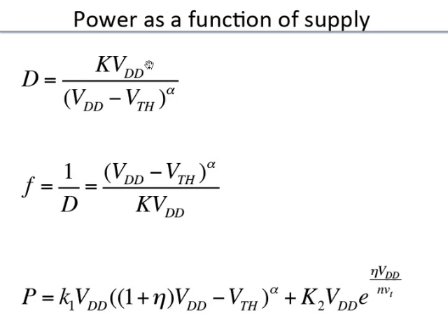If you recall the delay for a CMOS logic gate driving an output capacitance, the capacitance is its self capacitance plus wire plus the load capacitance. There is an average current, you can say, which the gate provides to either charge or discharge, and that average current is related to the saturation current, VDD minus VTH, the overdrive when the transistor is in saturation, raised to a factor alpha.